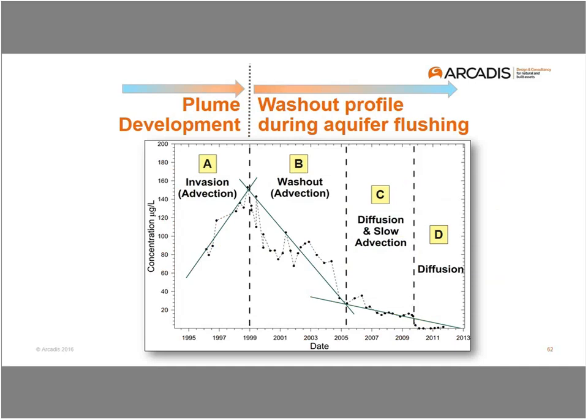So maybe there was an excavation or an in situ mix or some source area treatment that addressed the LNAPL mass, and we're dealing with the LNAPL composition phase. The mobile fraction is diluted by upgradient impacted water, and we see this as a decrease in concentration, but there's also ongoing establishment of equilibrium with the storage in the immobile fraction.